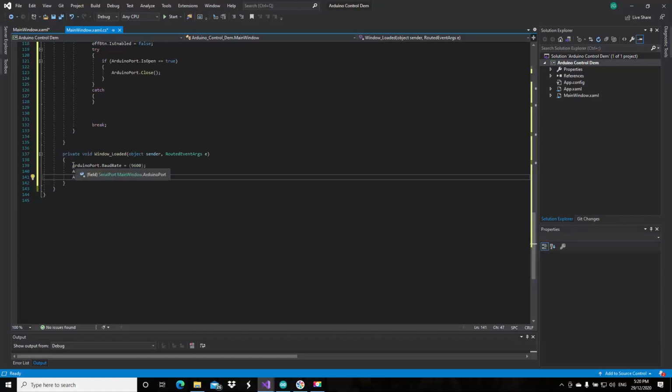All right. So baud rate, that's the speed. When you program your Arduino, you might use 2400 or 115,200 or something like that. In my case, my Arduino is programmed at 9600, so the baud rate for this application would be 9600. If you want to use different speeds, you can make another combo box on the other window and fill it with the different baud rates you want available, but that's not stored in memory anywhere, so you'd have to type them in.